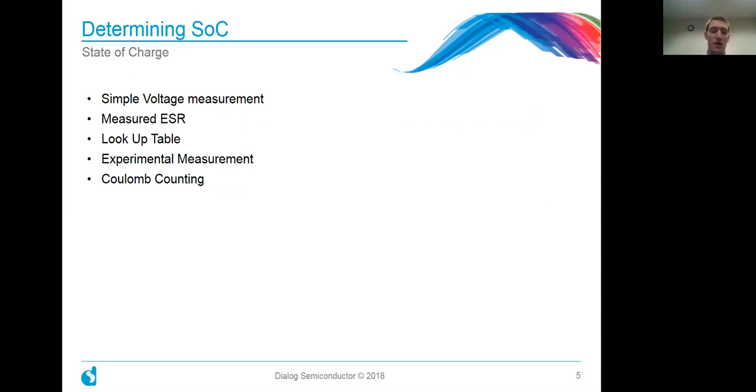Maybe you run 100 batteries over the course of your system to measure the worst case length that it can live, and then use that as a standard measurement, and you say never going to let a battery be left in the field for longer than that shortest amount of time. Finally, you could do Coulomb counting, which is what we're going to look at today.